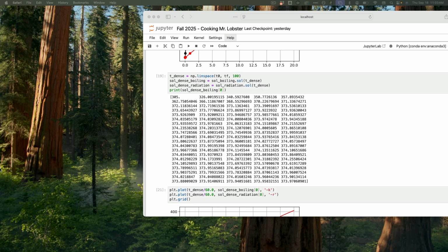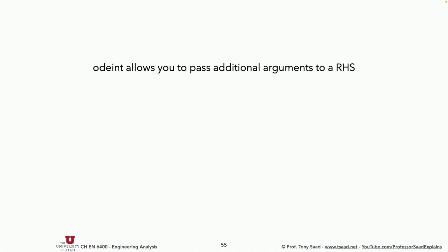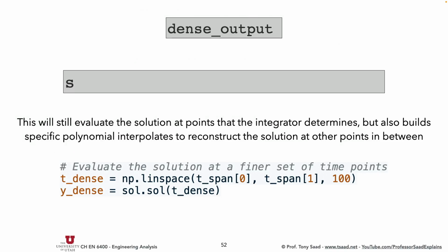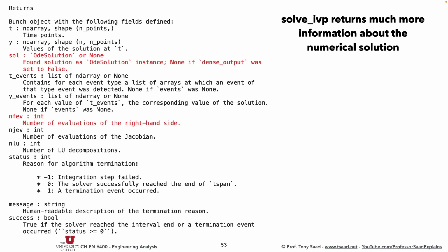Okay. And so you can do this and you can get a nicer solution. Then you can investigate the cooking or baking. You can play with the parameters and see which one is going to be faster. You're going to cook it in 2 minutes, by the time the person makes the order and they're out, and you can figure that out. You can play with the heat transfer coefficients, etc. So that becomes the physics problem where you as an engineer need to figure this out.